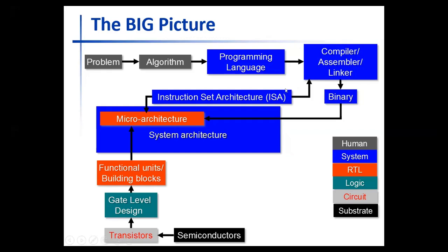So the actual microarchitecture is a circuit which is built to support a given instruction set like that. If the ARM architecture contains, let's say, 10 instructions, for the sake of simplicity, 10 very specific instructions, then an ARM-based microarchitecture will use various digital electronic circuits to support all those 10 instructions in actual hardware.